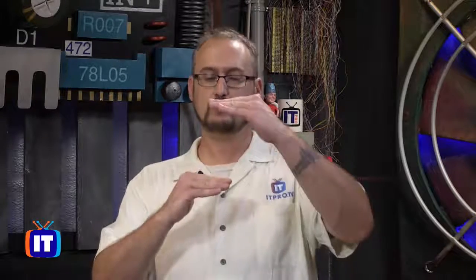And that's the same thing with the top of a CPU. And if we were to put that heat sink by itself down on the top of that CPU, then what we would have is actually an insulator. The problem is you need something that bridges the gap, right, the air gap in between metal on metal, and also helps to kind of smooth out those imperfections. And that's something that has quite a few different names. Commonly, we just call it thermal paste or thermal compound. I know I've heard people call it thermal goo, thermal putty, right, all different kinds of things.